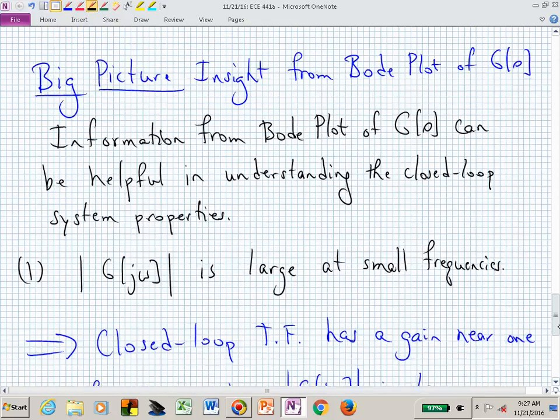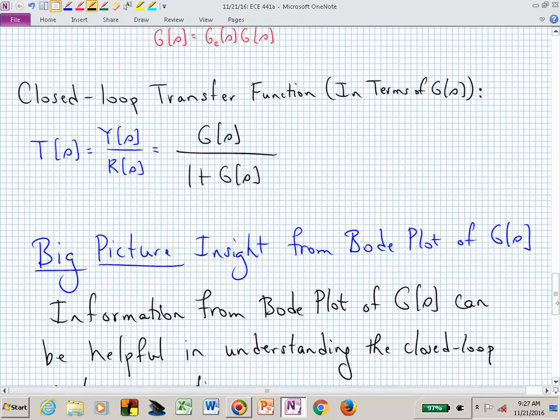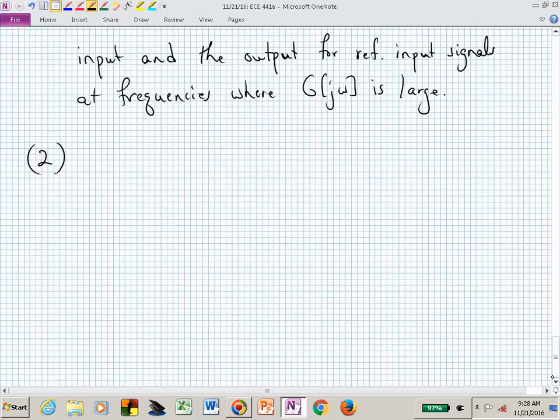What can we say about the stability, or what would we be examining in this closed loop transfer function if somebody wanted to know, is that system stable, or what's its behavior? What particular piece of this whole T of s would you be focusing on if you're wanting to know stability? The denominator, the 1 plus g of s. So now we want to look at 1 plus g of s, and if we have g of s as a function of frequencies, 1 plus g of s isn't that much different, is it?